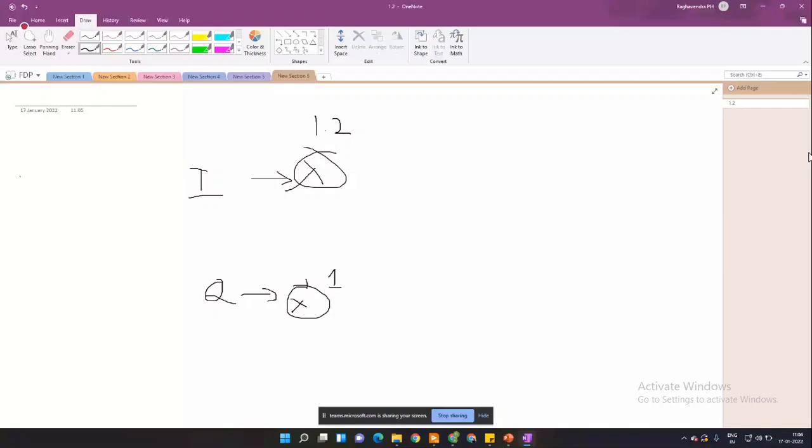These are still in digital format, so I can do some amount of signal processing on them. So I divide the I signal magnitude by 1.2, and for the Q I don't do anything. Now, since my I is divided by 1.2, by the time it comes to the mixer it will be I by 1.2, and Q by 1.